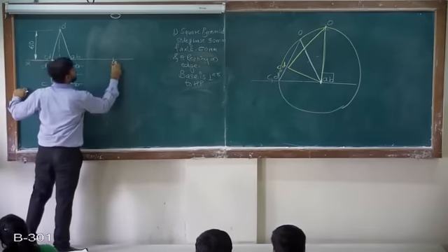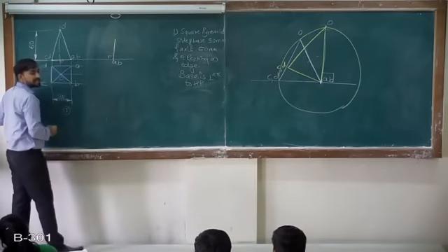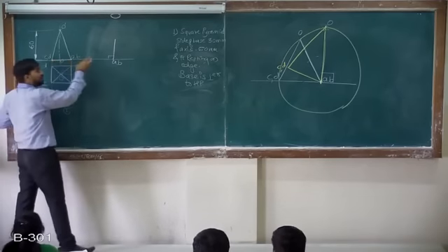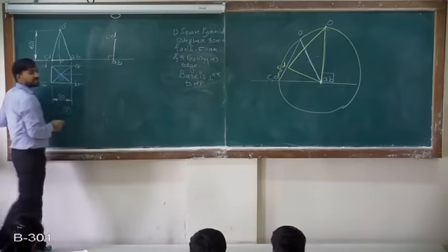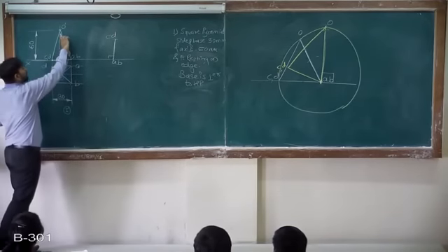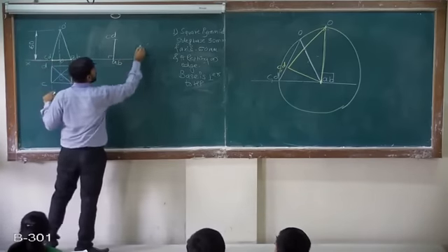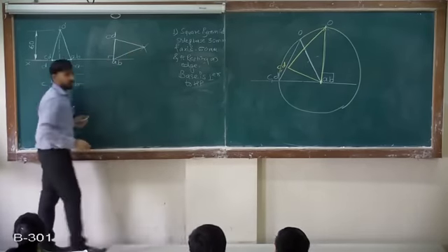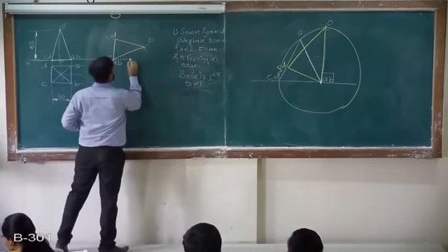So keeping AB here, take 90 degree as perpendicular base. Take this distance AB to CD. Mark from AB. Take this point as CD. Next, AB to O and CD to O. You just draw two arcs. Right? This is point O.